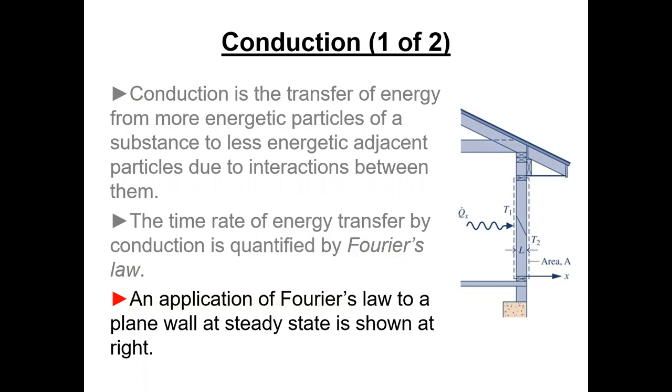The dashed line is just the control volume, or I guess you could say control mass in that case, because you don't have any mass moving in and out. It's just that section of the wall. You see T1 is warm because it's at a higher level, and T2, it's cold outside. If that's a homogeneous material, constant K, then you get a linear temperature profile at steady state.